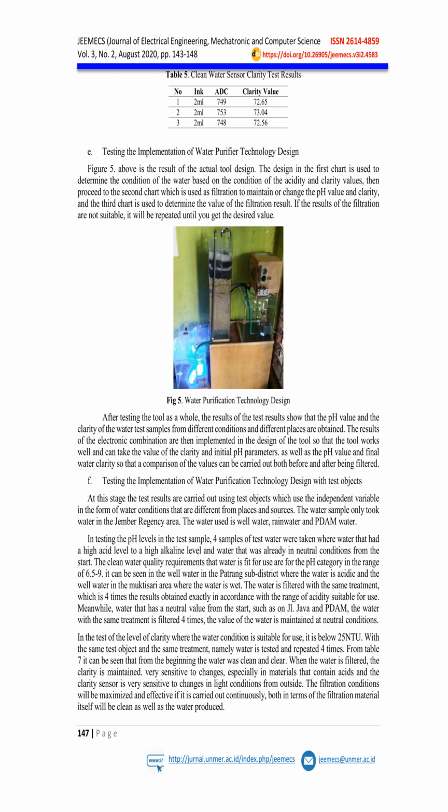In testing the pH levels in the test sample, 4 samples of test water were taken, where water had a high acid level to a high alkaline level, and water that was already in neutral conditions from the start. The clean water quality requirement for water to be fit for use is a pH in the range of 6.5 to 9. It can be seen in the well water in the Patrang sub-district where the water is acidic, and the well water in the Muktisari area where the water is alkaline.